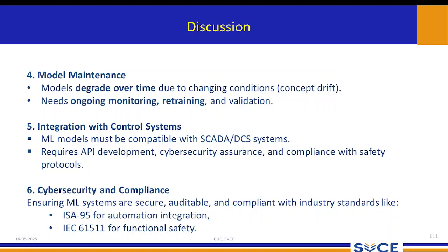There are a few cases where industrial exposure happened because of the failure of the sensors. The sensors are not properly maintained, and they are not showing any alarm. The level of the tank has increased more than 50%, for example. If it is 80% or 90%, they still show less than 50%. Obviously, the control room DCS system failed, and that will lead to a disaster. You might have seen the US disaster caused by the control system failure. What happened? It is not control failure in the sense that the sensor reading was not reflected back in the control room.